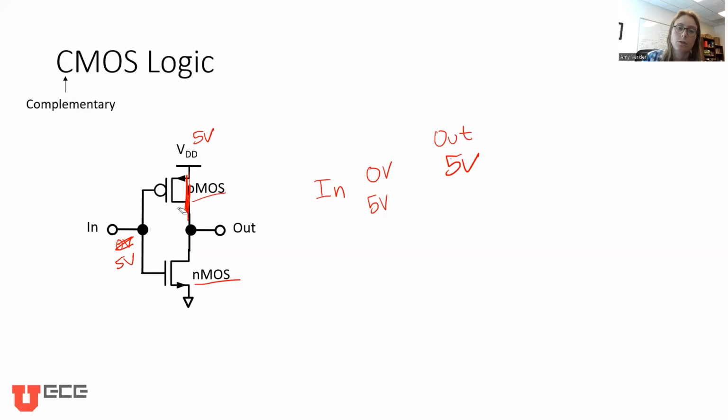Okay, so in that case, this transistor turns off, so no connection. And 5 volts turns this one on, so now we connect to ground. So this is doing basically the same thing as the last circuit, right? We're turning a 0 volt into a 5 volt, so an off logic into an on at the output, and an on, or a 5 volt, into a 0 volt, or an off. So this is called an inverter. This would also implement a NOT logic gate.